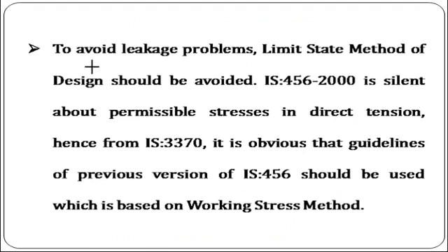Also, to avoid the leakage problem, the limit state method of design should be avoided so as to get an uncracked section. As per IS 456, whatever stress is generated should be within the permissible limit in case of direct tension or tension due to bending. And for that purpose we have to specially refer to IS 3370, or the guidelines given in IS 3370 as we discussed earlier.